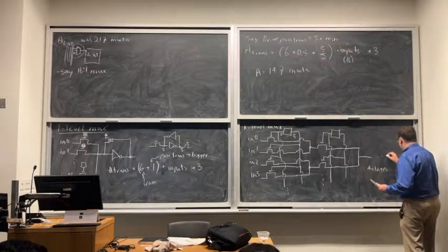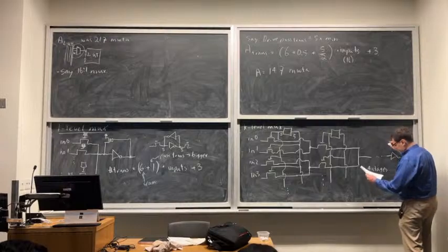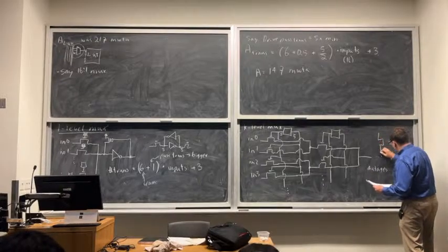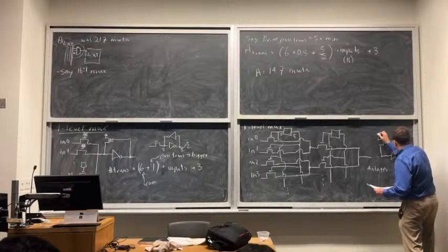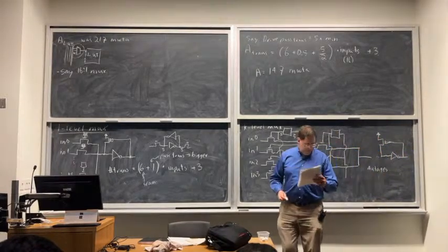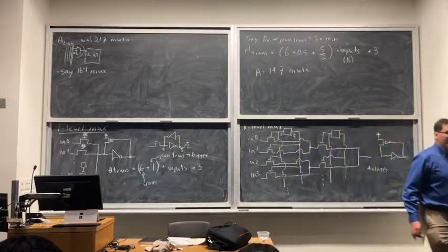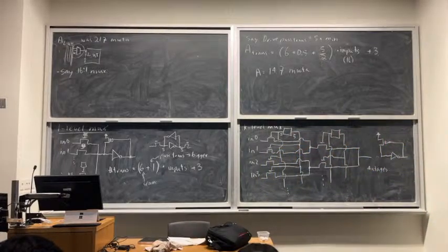And then at the very end, I need the same thing I always need. I need an inverter. And I need this keeper or pull-up transistor. Okay, and there's a whole bunch of stuff down below that I haven't shown. Right? I just have to repeat this multiple times, but it'll take me forever to draw that. Does everybody get the structure? So it's like a logarithmic tree.